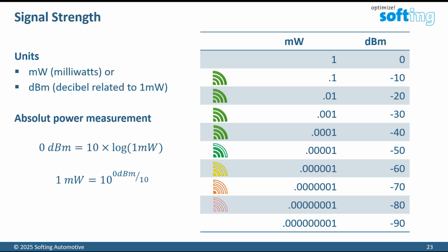And there's also the signal strength in Wi-Fi. It's quite an important value. We know this symbol from our cell phone or a computer, but translated it means the value of the received energy in milliwatt or dBm. When you write it in milliwatts, you see that there are a lot of zeros. So you use the logarithmic scale in dBm. It's the value related to 1 milliwatt. And there are some rules of thumb, that say up to or down to minus 40 dB, you have a very good signal.